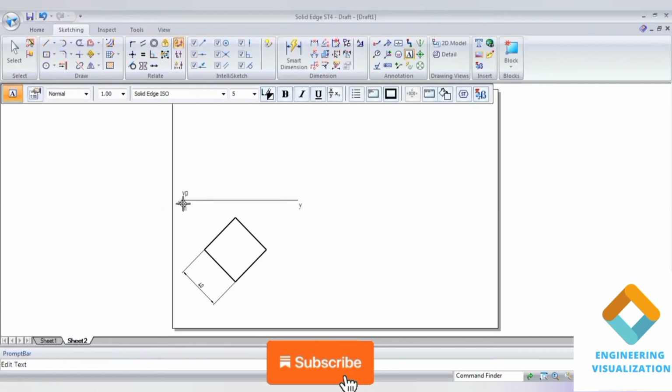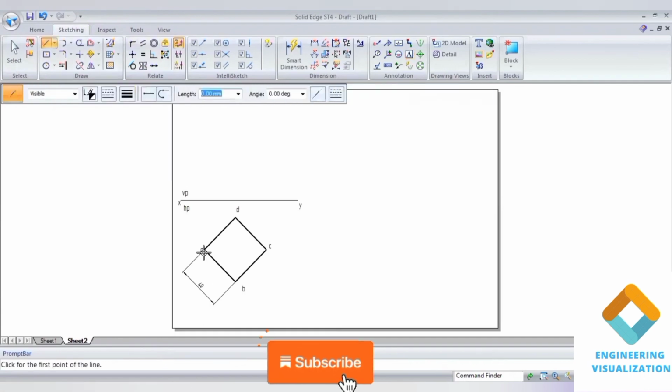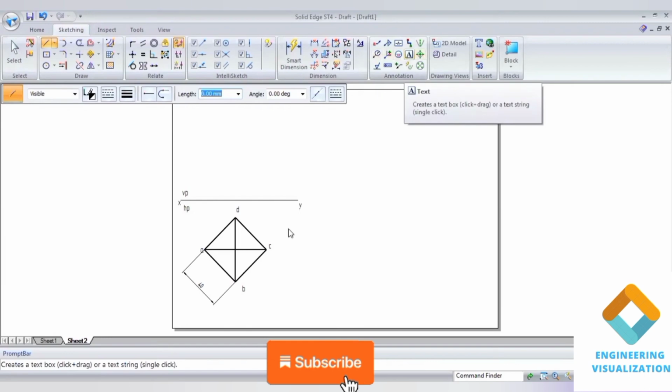Write XY, HP, VP, and draw the projection lines upward to construct the front view. Here the top view notations can be written ABCD. Since it is a pyramid, we need to draw the slant edges with thick lines. If it is a prism, they should be thin lines. You all should know this difference. So thick lines we have drawn.